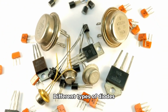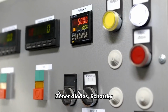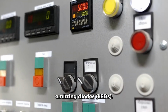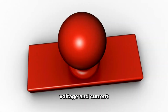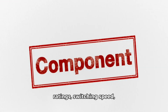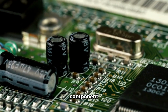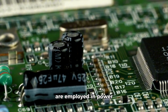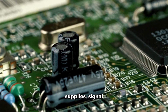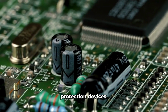Characteristics: different types of diodes include rectifier diodes, Zener diodes, Schottky diodes, and light-emitting diodes (LEDs). Each type has its unique voltage and current ratings, switching speed, and intended application. Understanding component characteristics and applications. Applications: diodes are employed in power supplies, signal demodulation, voltage regulation, and as protection devices.